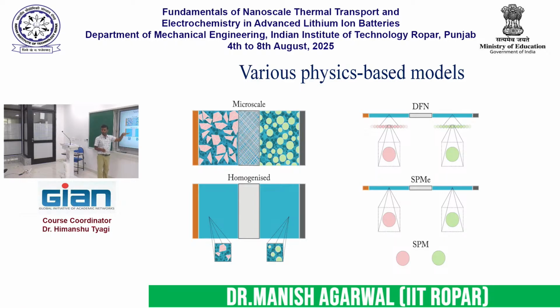I will go into the detail as we go along; right now I'm just giving the overall picture. Then there is a model called the DFN model, or more popularly known as the P2D model. This is perhaps the most popular battery model. Whenever you do electrochemical analysis in software like COMSOL, by default you are using the P2D or DFN model.